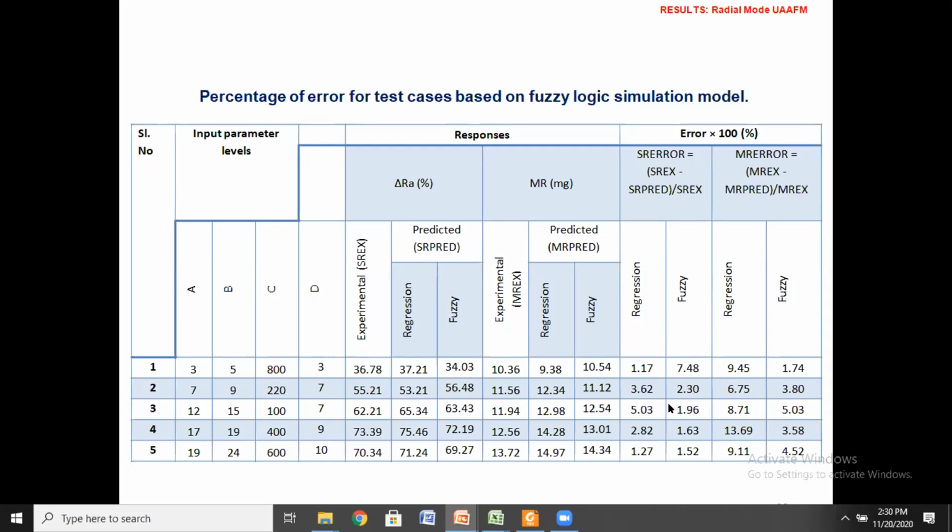You can find out whether your data is valid or not by using other tools such as the fuzzy model, right? So this is how I have conducted a few experiments and a study on the fuzzy model in MATLAB. It is readily available in MATLAB. One can try using these AND/OR rules. After completing your set of experiments based on AND/OR rules, you can slightly change the logic. The controller will give you the predicted value, and based on the experimental value, you need to compare the predicted value and generate the error. You can see the error percentage, right?